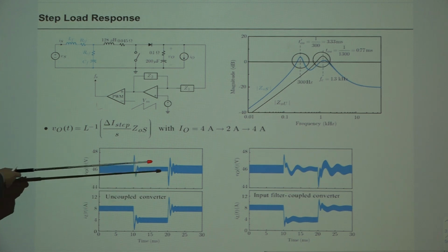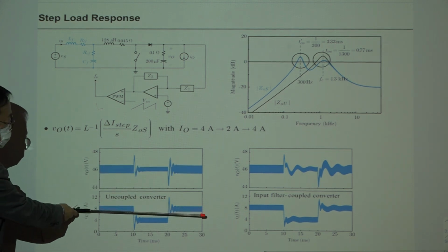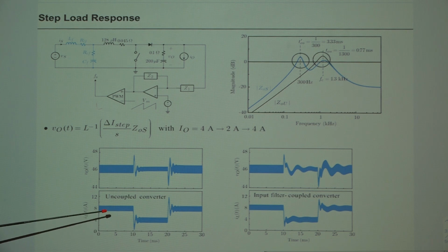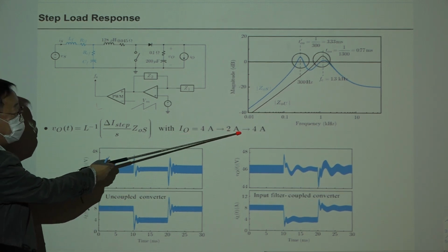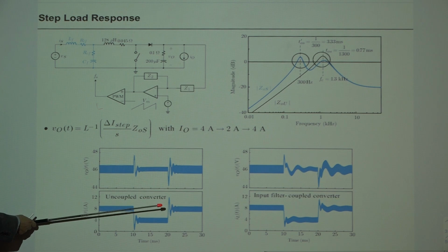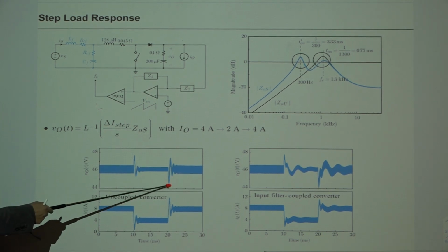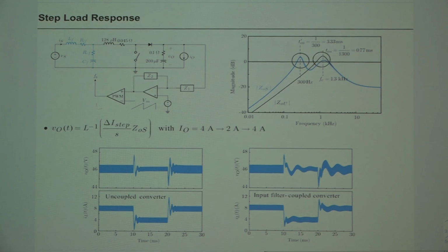So this is the transient response of output voltage due to this current change, IL. Okay, this is the output current change, and this is load current. This is a boost converter, so they are different. Load current and inductor current are different, all right? And it has some low frequency oscillation. This is due to what? Small phase margin. You are using voltage mode control on a boost converter, which is forbidden in general.